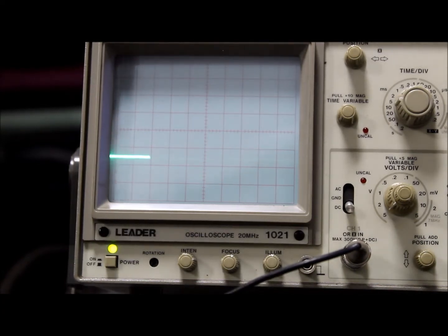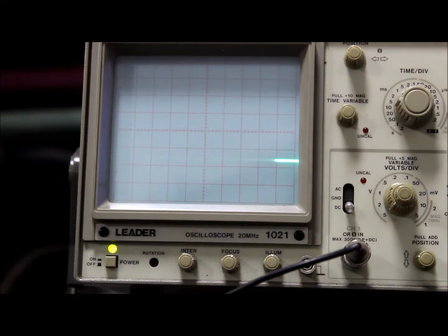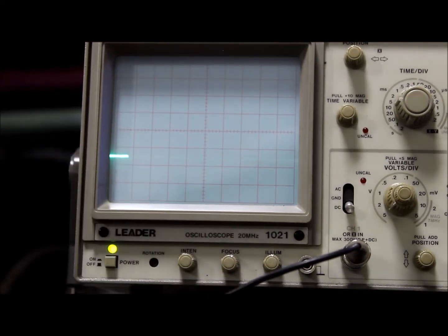So we can see now it's reading just over 12 volts DC. So we're on the negative side, but it's not grounded, so we're seeing the voltage that's supplied to the injector. Whenever it's grounded, that should be pulled down to 0. So I'll start the vehicle. Might be a little hard to see through the camera. We'll see if we can find the pulse width or where the injector is actually turned on.